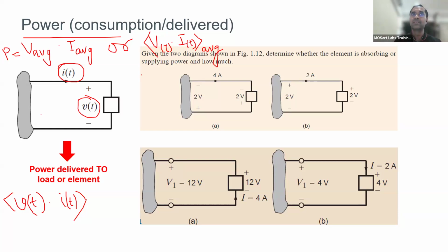And the answer to this, option A. Yes. I believe the latter one. Yeah. So the better or the more accurate way of doing this is the second option. Okay. But keep in mind, here the assumption is that the change in current or change in voltage is reasonably small when compared to the overall average mean value. So this means if you had 600 millivolts and then you had 10 millivolts plus minus something, then the variation is smaller than your mean.